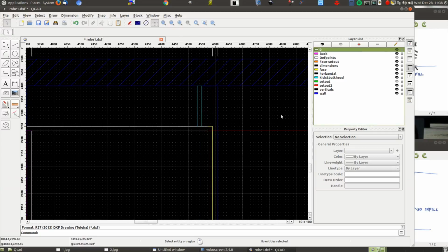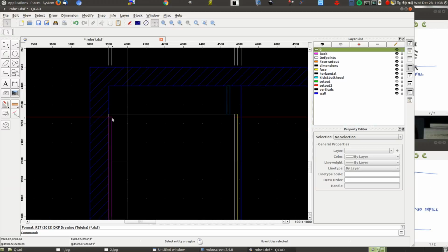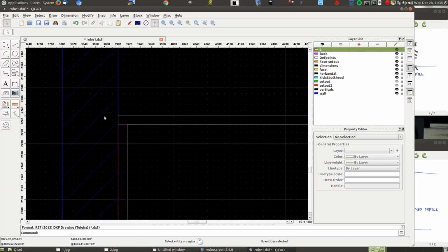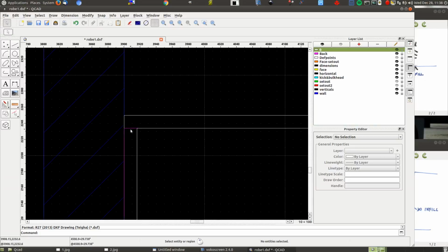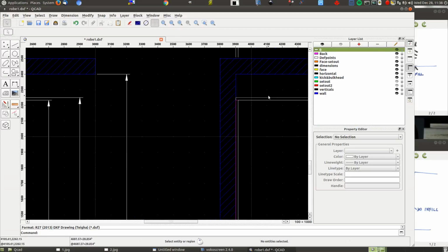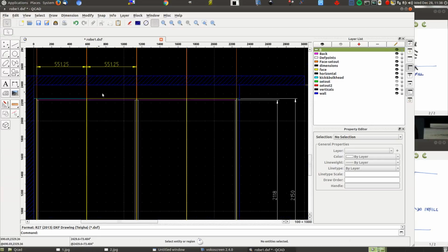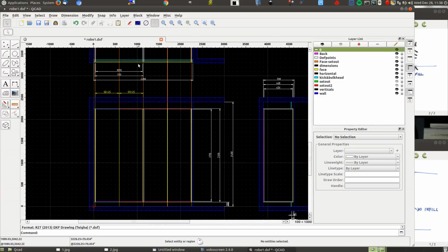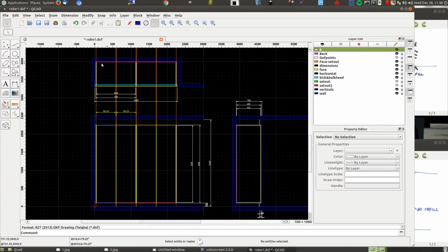There could have been confusion as to whether I stop, or whether I have the back underneath the top or going through. If I'm not consistent with my thinking, with my drawing across the three views, I can leave myself in quite a pickle, having three different sizes for a single component, two different widths and/or two different heights. So there's a potential for quite a bit of lost information.